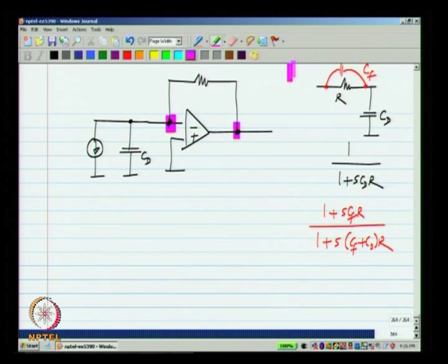So, either way, the result is that in the frequency domain you have a zero that provides phase lead, or in the time domain you have an advance compared to what you had earlier, advance meaning a negative delay. Of course, the delay of the circuit is not negative, it is just less than what it was before.